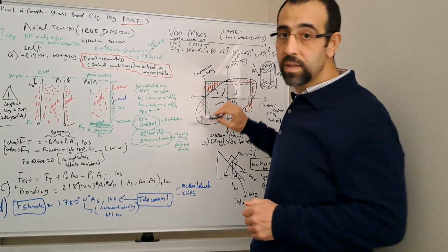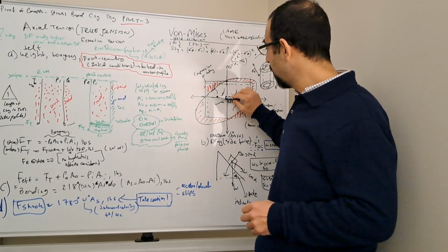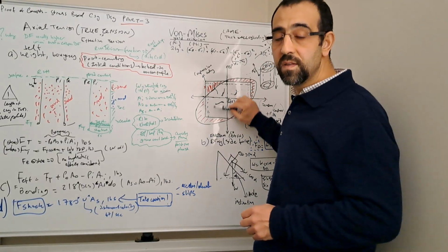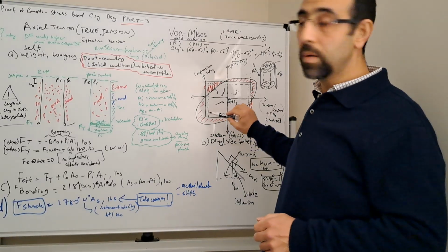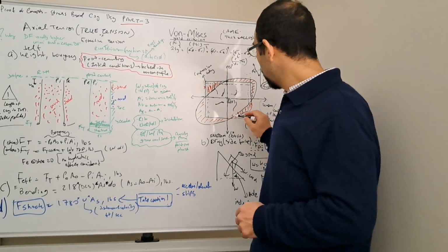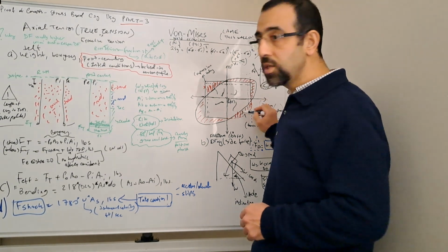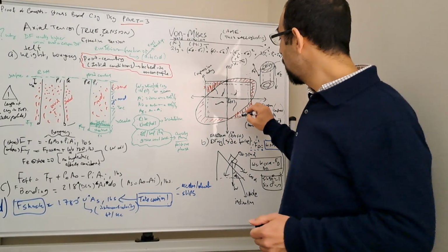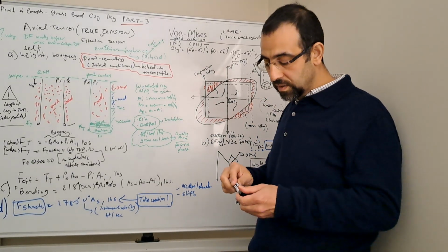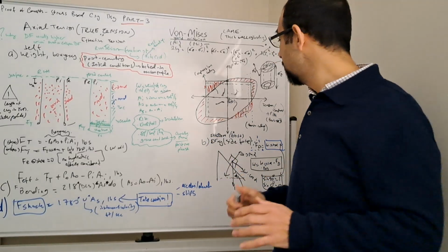And in part number 2, we covered the collapse regimes, in the bottom part of this design limit plot with a negative delta P, so the external pressure being higher. And then over here we covered the impact of the tension on the collapse rating, on the collapse derating, let's say. If you remember, this was completely different from the temperature derating on the yield strength of the pipe.